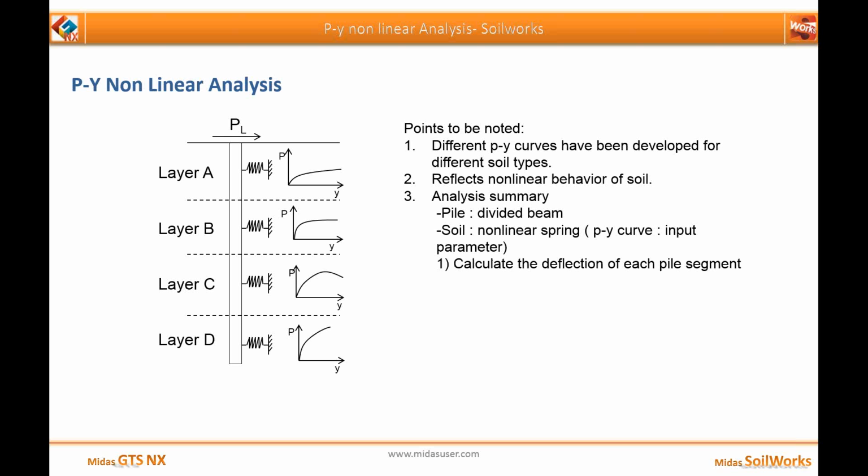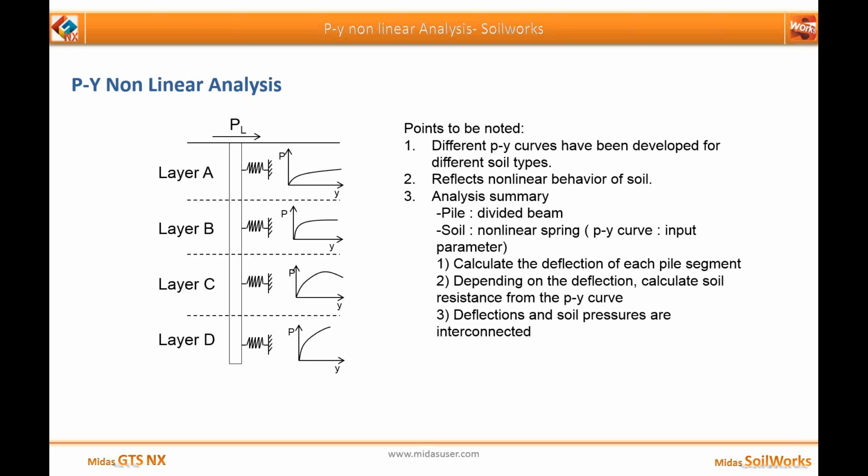Now having obtained the nonlinear spring PY curve for each layer, we obtain the deflection at each pile segment after applying the load, and then depending on the deflection one calculates the soil resistance from the PY curve. Deflections and soil pressures are interconnected, and iterations are performed to obtain the correct value of displacement for that particular layer. This is based on the finite difference method.